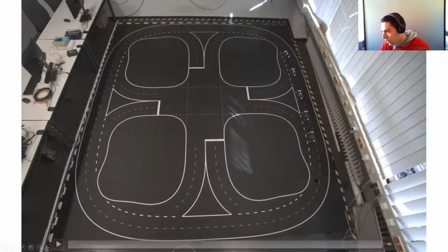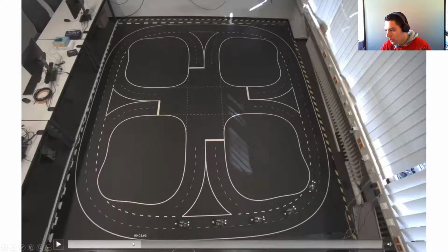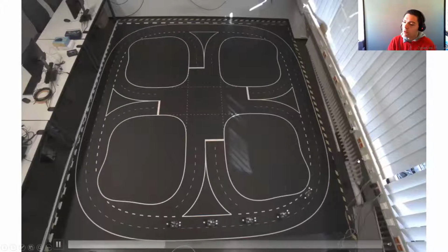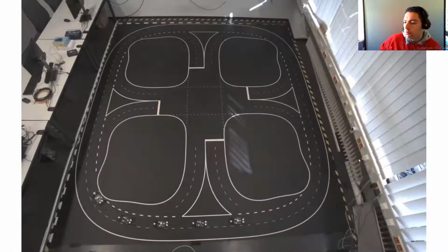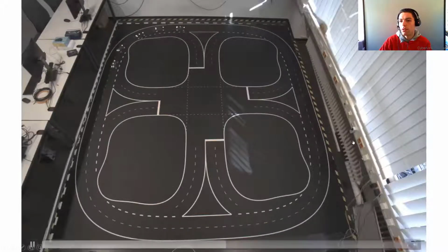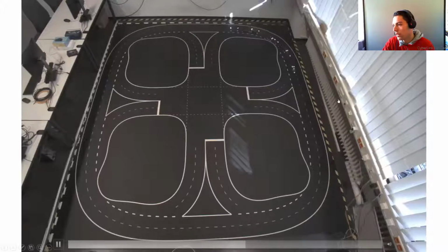A special thing in the simulation or in the video that I wanted to point out. I think it's in this corner where you see vehicle 3 having a bit of a fluctuating position between vehicle 2 and 4. You can see it approaches vehicle 2 and then it goes a bit backwards. So we could maybe tune the weighting matrix a bit more towards position or reference control instead of following the reference velocity.